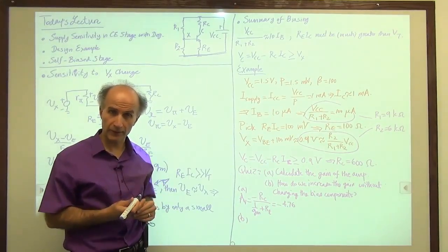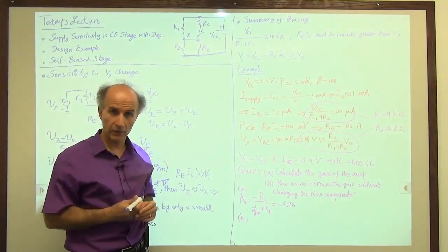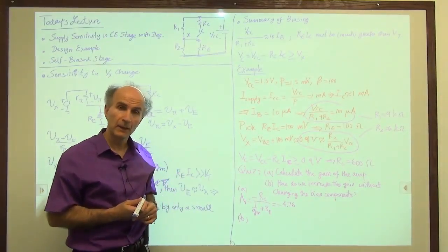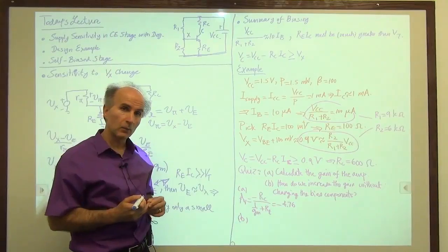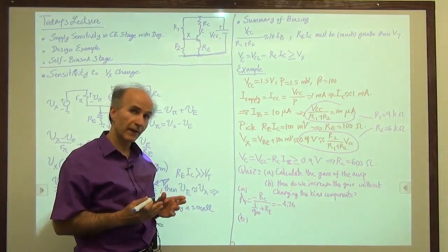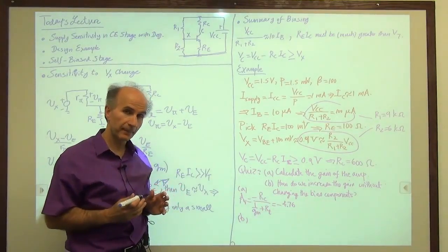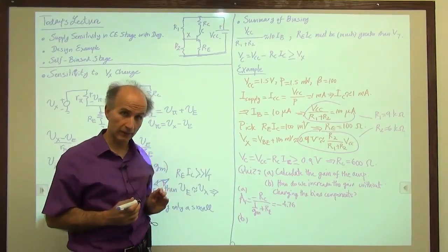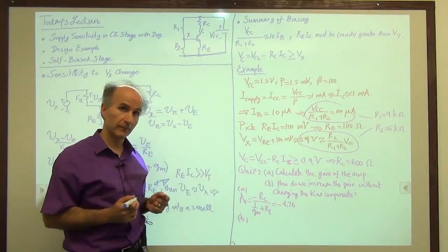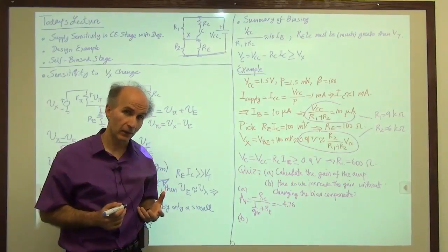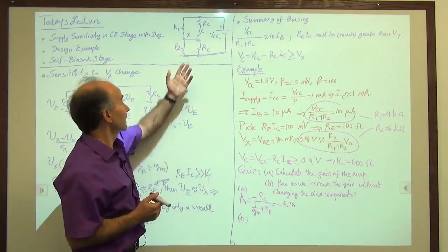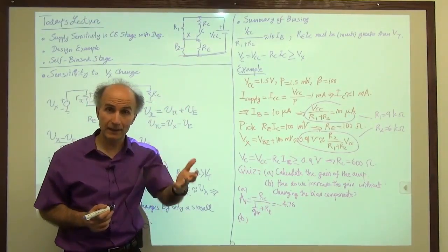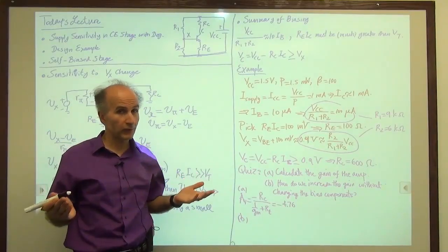Goes up to 5 megahertz. Well, this is a high definition camera, so maybe a little more. So the point is that when the signal comes in, it's an AC signal. It's not DC. If it's an AC signal, we want to increase the gain of the circuit for AC signals. We don't have to increase it for DC.